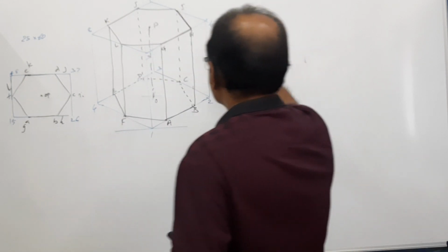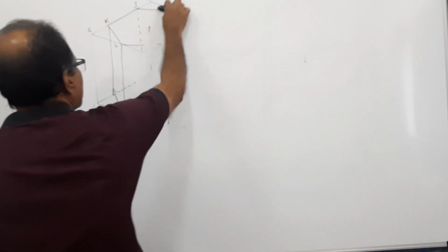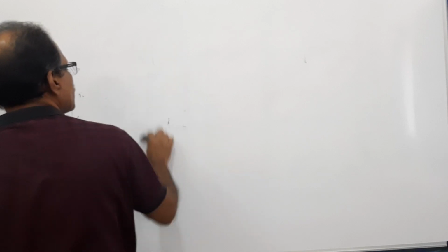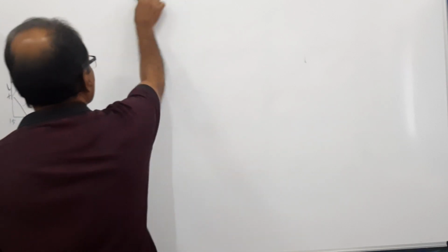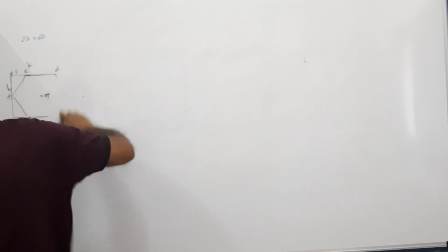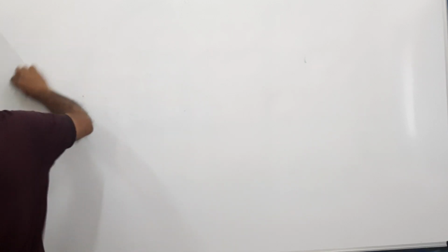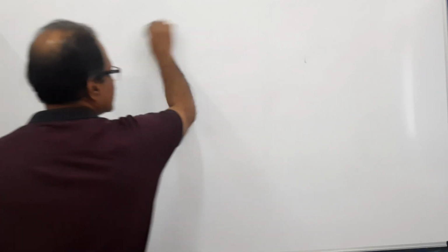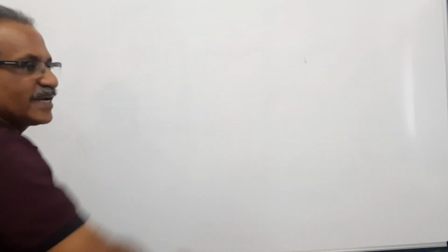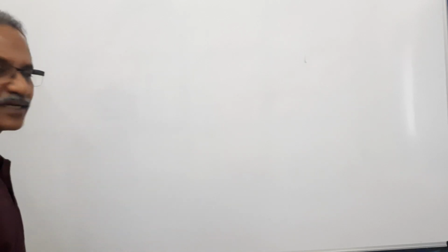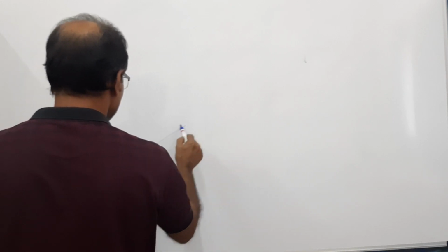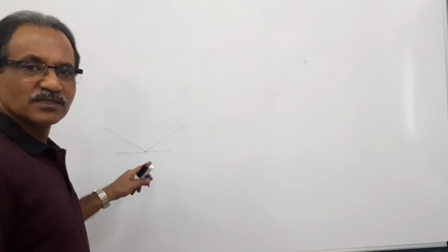If you assume a cylinder 50 mm diameter and 60 mm tall, standing on its base, how will you draw that? We have already learned the four-centered method of drawing isometric circles. A cylinder has two circular faces, correct? So what you do is, draw a rhombus. If the cylinder is 50 mm diameter, draw a rhombus, 50 mm side,